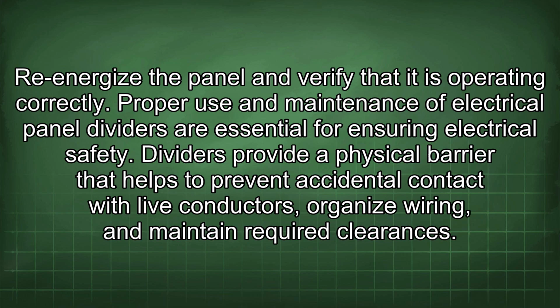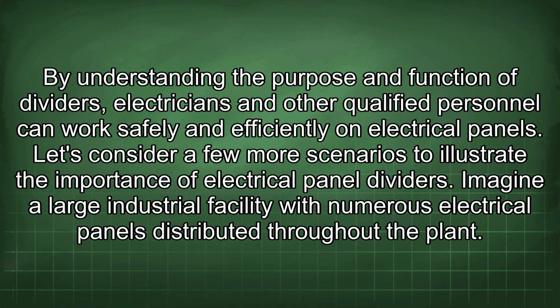Proper use and maintenance of electrical panel dividers are essential for ensuring electrical safety. Dividers provide a physical barrier that helps to prevent accidental contact with live conductors, organize wiring, and maintain required clearances. By understanding the purpose and function of dividers, electricians and other qualified personnel can work safely and efficiently on electrical panels. Let's consider a few more scenarios to illustrate the importance of electrical panel dividers.